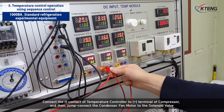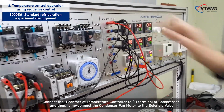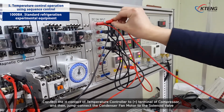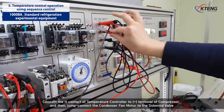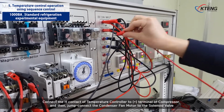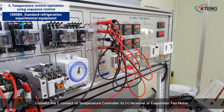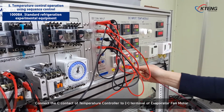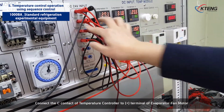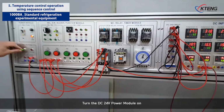Connect the H contact of temperature controller to the positive terminal of compressor, and then jump connect the condenser fan motor to the solenoid valve. Connect the C contact of temperature controller to the positive terminal of evaporator fan motor. Turn the DC 24-volt power module on.